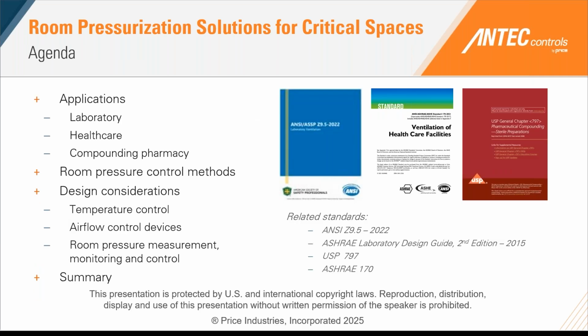The agenda for today will also include covering the applications for laboratory, healthcare, and compounding pharmacies, discussing different room pressure control strategies and methodology, and then finally discussing some design considerations, including temperature control, airflow control, and selecting the correct room pressure measurement, monitoring, or control strategy for these critical spaces. Standards that we're going to be referencing in today's presentations include ANSI Z9.5, ASHRAE Laboratory Design Guide, USP 797, and ASHRAE 170.